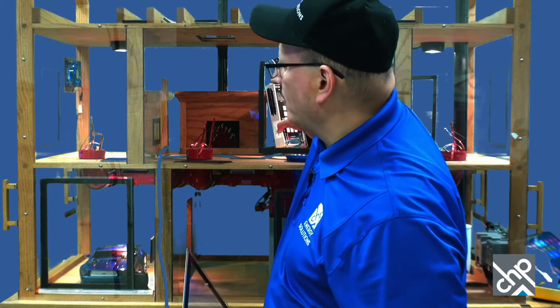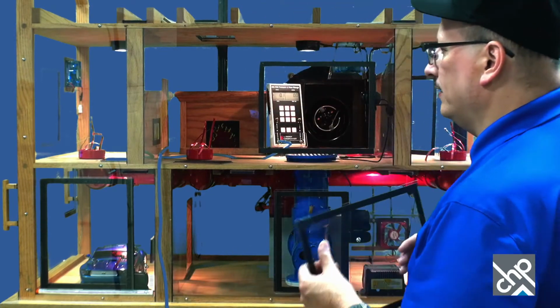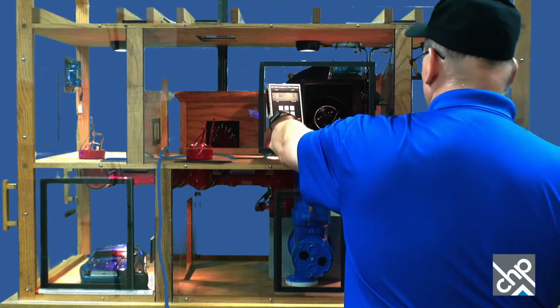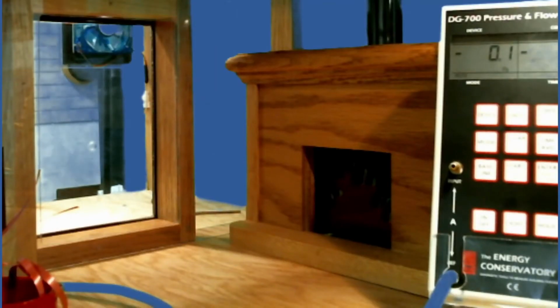I'm going to turn the manometer here, hopefully where we can see it. And if I need to move in every now and then, I'll do that too. I'll be able to go right into the living room there, and we should be able to see the number okay. We've got two numbers, but really the only one we need to see is the one on the left. And we're going to set this up to be CAZ with reference to the outside.